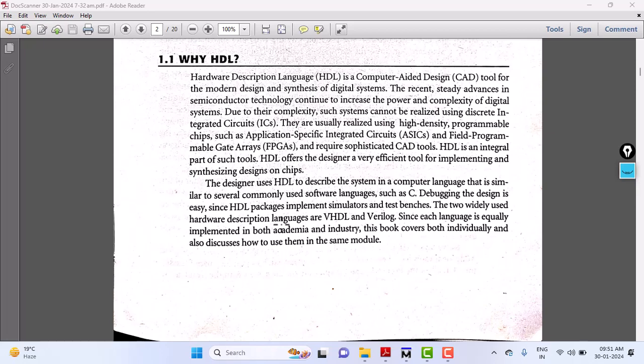Depending on the application. You have to see the application. Suppose I give you a project like a simple automatic door opening and closing project, which one will you prefer? A simple microcontroller. You don't want to go for FPGA, right? If I give you something like an IIR filter design or a FIR design, a fast Fourier transform design, will you go for a microprocessor? Will you go for a microcontroller? You normally go for FPGA.